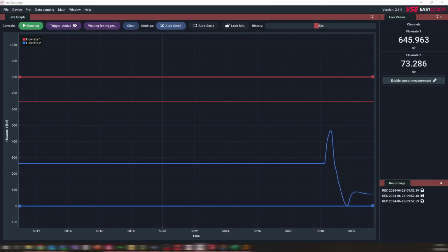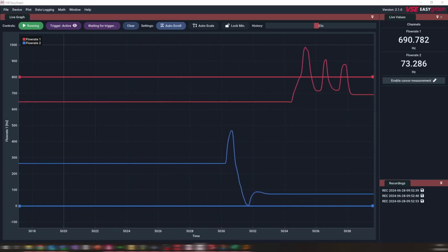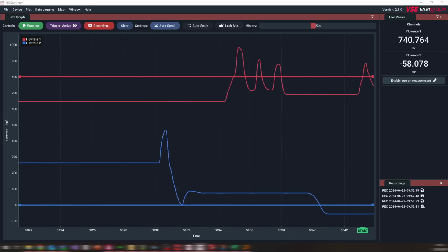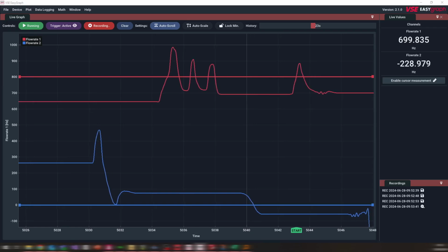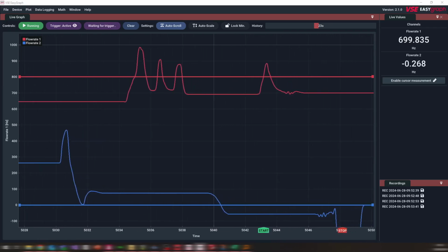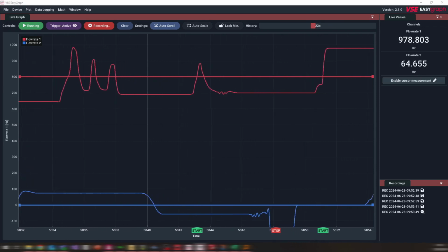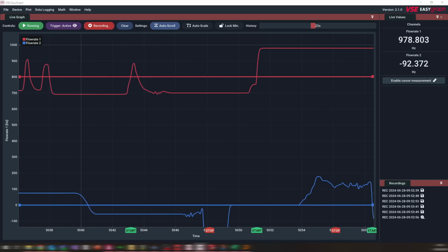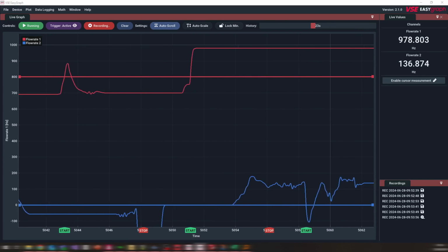So when we now leave the second flow meter value above 0 and hit the line at the top, nothing will happen, no trigger will happen. But when we go below 0, the blue line, then the trigger will really trigger the process. We can use this to combine both channels. And it's not only possible to use the AND operation, you can also use the OR operation, for example, to trigger on the pressure of the analog input and other stuff you can think of.